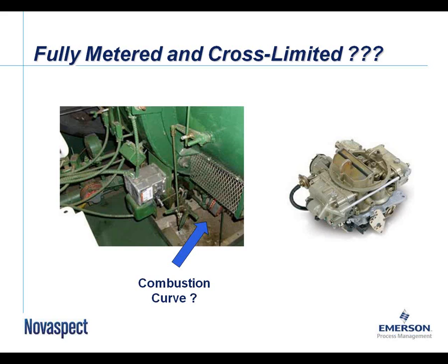So you link the air damper directly to the gas valve, and then that gas valve has a series of screws in it that you adjust so that as it turns and goes up in load, the boiler goes up in load, the screws are pressed in farther, giving you more gas flow. And this is analogous to, keeping the car analogy going, a carburetor in a car. I had a 76 Cutlass Supreme that had a 4-barrel Quadrajet carburetor, and it worked pretty well.